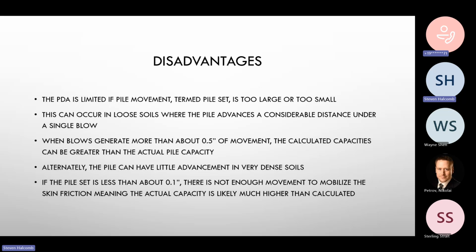And so if a contractor's doing 120 blows a foot and we've assessed the hammer's working fine, it's not a hammer problem, then they're usually entitled to more compensation or some alternative ways to advance the pile. It was a surprise to us and to them. So pilots, special pile excavation like cleaning out the tips if you can, or getting a bigger hammer, or whatever you can do to advance it. It's generally not on them if it's into difficult driving.